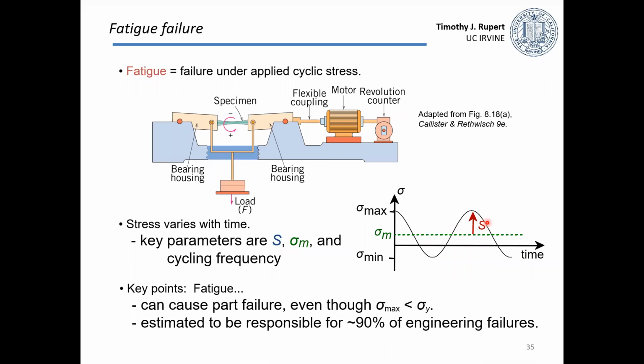So some of the key points of fatigue is that this type of loading can cause failure even when the maximum stress that's applied is less than the yield stress. Okay, and really a practical consideration is that it's been estimated that roughly 90% of engineering failures come from fatigue. So it's a very important type of deformation.